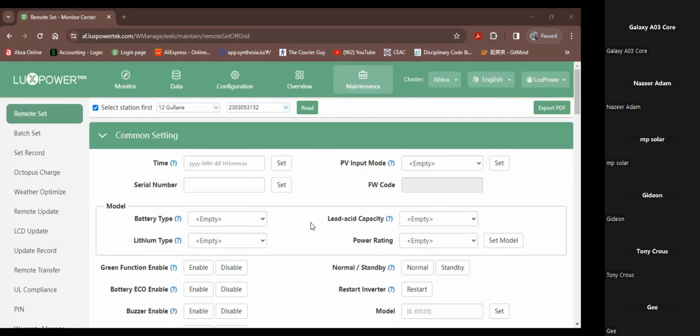So if you had put up 6.6, then the chances of you exceeding that and going into an overload on your voltage bus is high. So I always recommend that, and this is just my personal choice, you don't have to follow that, but I always go 10% less than what the design rate is. So if it's 6.6, take 10% off, take 600 watts off, and then maximize it at 6 kilowatts maximum. So put in 3 kilowatts and 3 or 3.2, whatever the case may be. And it just simply means that for that 1 or 2 days, or the slight chance that you might have a spike, that your design has